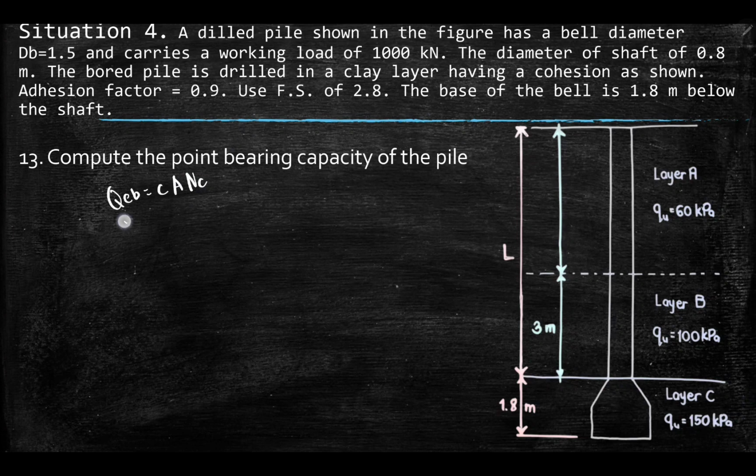So again, when we talk about the end bearing capacity of the pile, ang kino-consider natin dito is the pile tip, kung saan nakapatong yung ating pile tip. So yung condition na gagamitin natin dyan is the 1/2 of QU, which is 150, times area nung considered pile tip, which has a diameter of 1.5 meters.